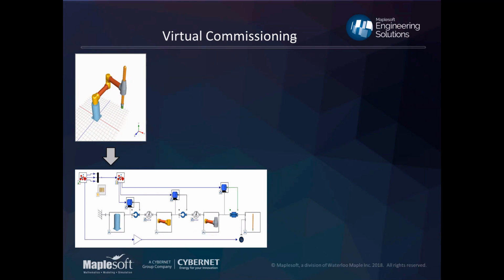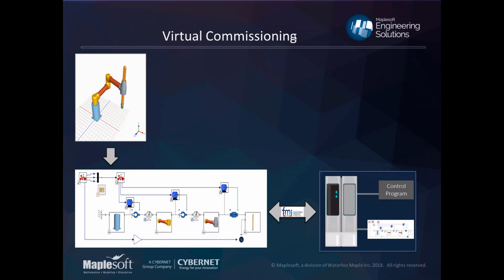And in MapleSim is where you actuate that and you bring it to life. So you can see below now, we've got these components that are the different bodies. But now we've added in joints and motors, and even we've specified a motion path for that. Once you've got an actuated model, you can do all sorts of testing from within MapleSim.